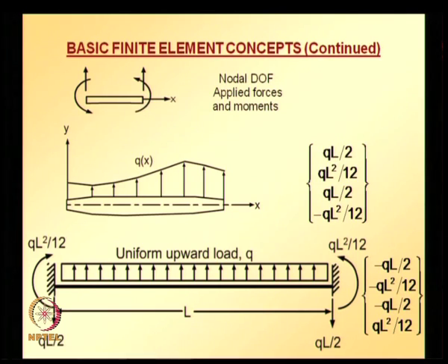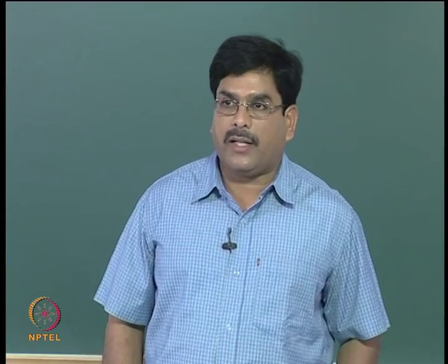And now once we calculate the nodal values, that is V1 theta 1, V2 theta 2, what we usually do to analyze any beam problem is write the element equations and then assemble them in the usual manner depending on element connectivity. Whatever element equations we derived, we have to assemble them for each of the elements.